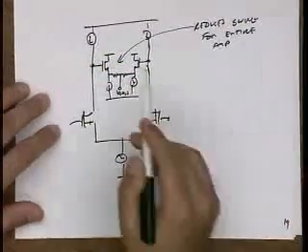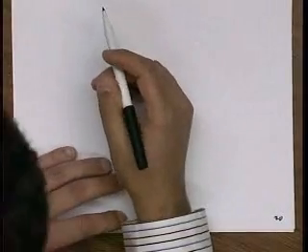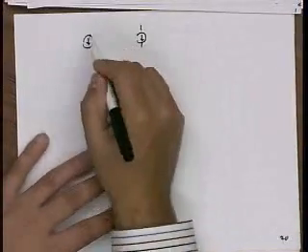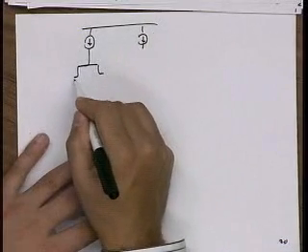Let me mention, so this approach here uses resistors. As we know, we kind of don't like resistors. In a typical CMOS process, they're not really available. So I'd rather not use resistors. So here's a circuit that doesn't use resistors. Actually just uses two diff pairs.